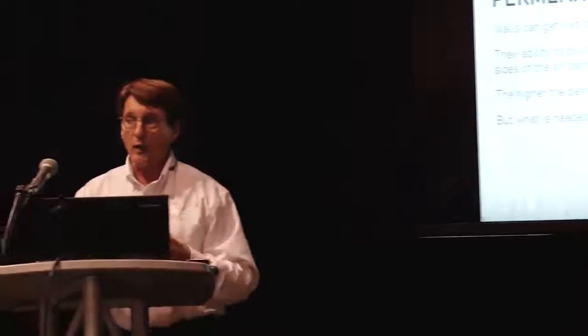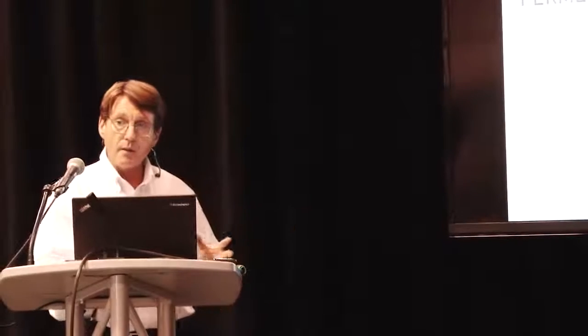So considering all this, there was some testing that was done. What we know for sure, walls get wet. It rains or we have a vapor drive. The question becomes, can they dry out? We know different materials have the ability to allow it to pass through, but sometimes we're finding that it's other assemblies beyond the air barrier or inside that are going to have more of an effect on the permeance of the wall than the permeable air barriers themselves.